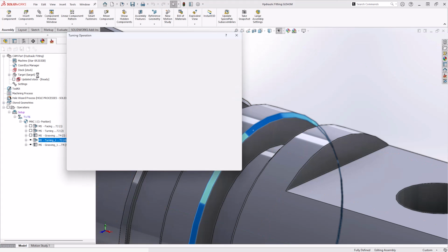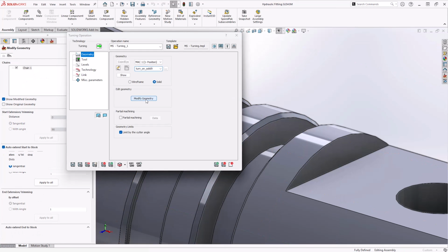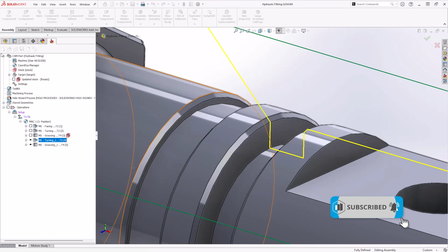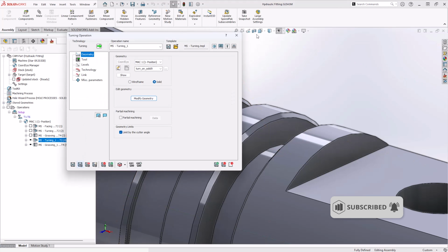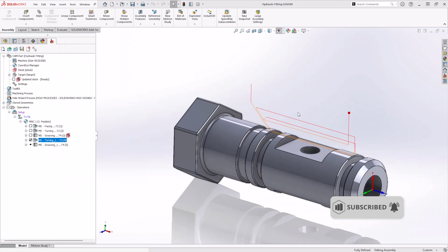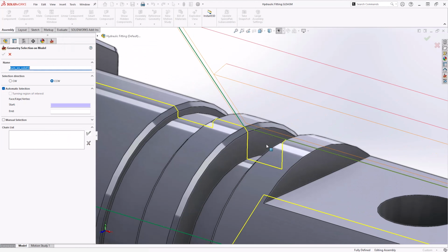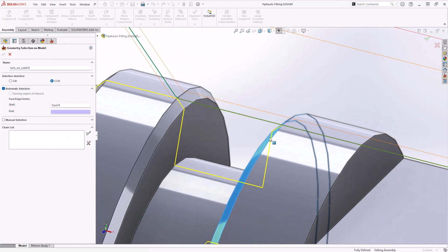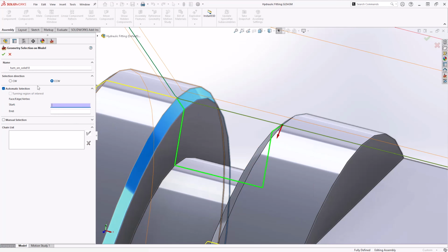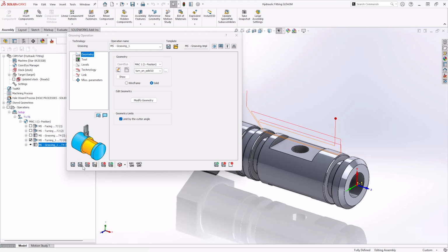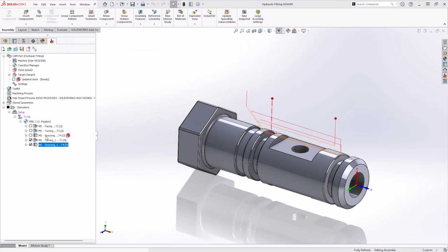As you can see I'm now doing the first turning operation. This again makes sure that as you go through cutting the part, we're making the most out of what the sliding head lathe is capable of with the rigidity of the guide bush, and we're keeping consistency as our approach is the same every time because we're using the same toolpaths over and over again. Again, you can see this allows us to build up what could potentially be a more complex model very quickly.